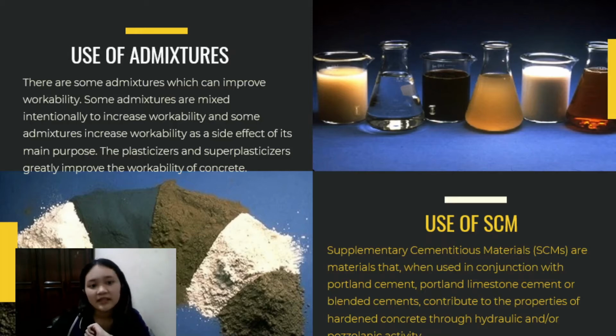Use of supplementary cementitious materials. There are many supplementary materials used for improving quality of fresh concrete. Some of these, like fly ash, improve workability, and some of these, like steel or synthetic fibers, decrease workability.